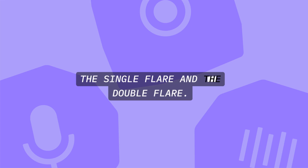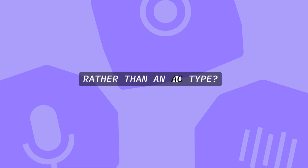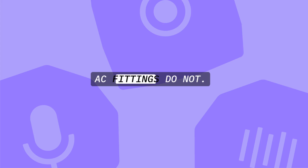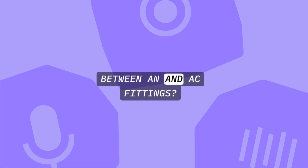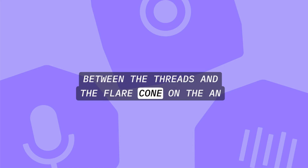Describe the two types of flares commonly used on aircraft tubing. The single flare and the double flare. How can you determine if a fitting is an AN type rather than an AC type? AN fittings have a shoulder between the flare cone and the end of the threads. AC fittings do not. What are the most significant differences between AN and AC fittings? Sleeve length, thread pitch, and the shoulder between the threads and the flare cone on the AN fitting.